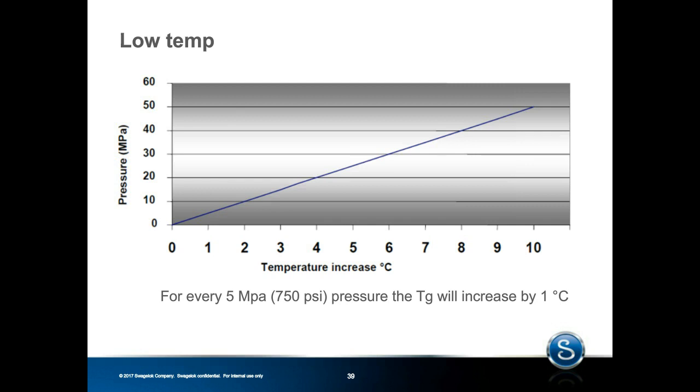Elastomer materials are very flexible when they're above the temperature that's referred to as the glass transition temperature. When an elastomer material is below the glass transition temperature, it will be very rigid and segmental motion of the polymer chains is stopped. Therefore, when an elastomer seal material is below the glass transition, it is not effective as a seal material because it's not able to have